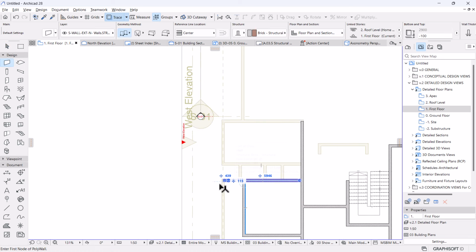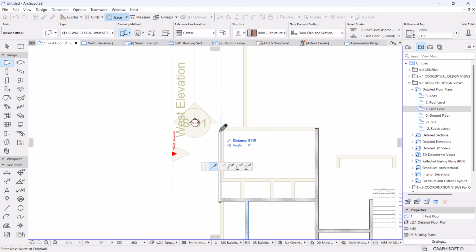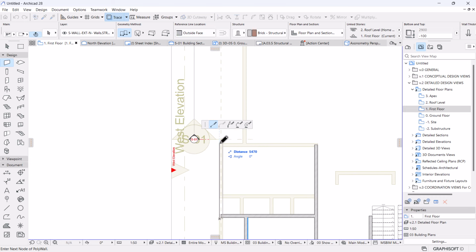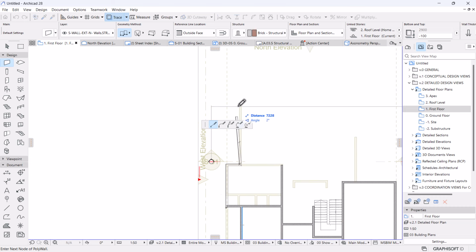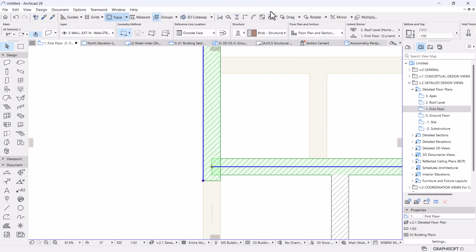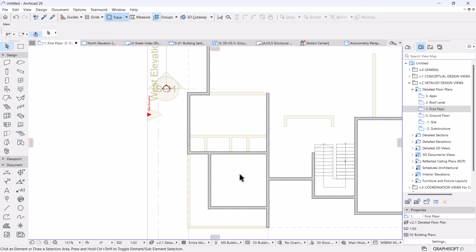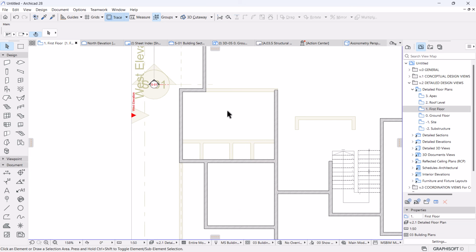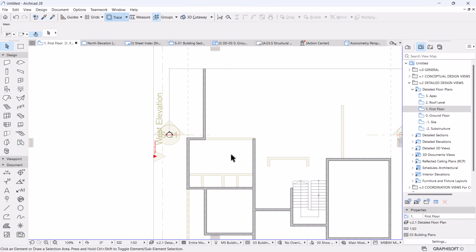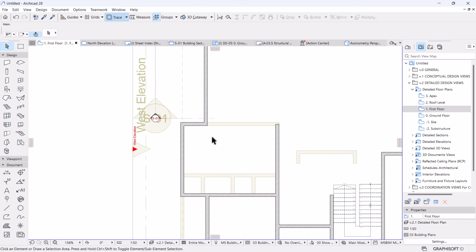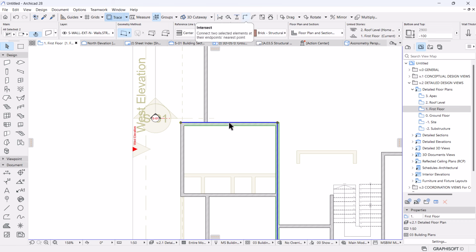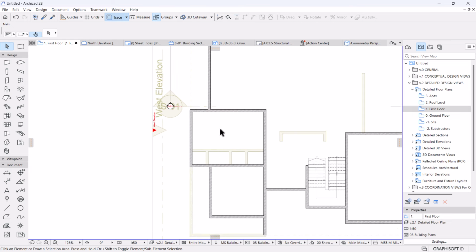So I'm going to draw another wall going all the way. Let's change the reference location to the outside, yes, and then stretch it to somewhere there, and that way you can go also like that. Then I'm going to select this and intersect. Okay, so we have this space for the pajama, and then the next space will be the actual bedroom. Then following will be the closets here against this wall. So I can even take this wall and intersect to enclose the bedroom.